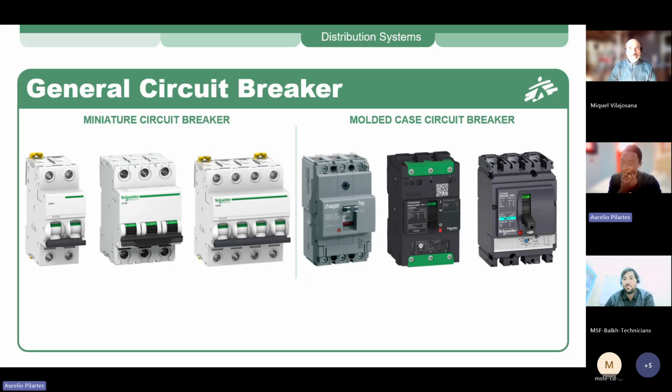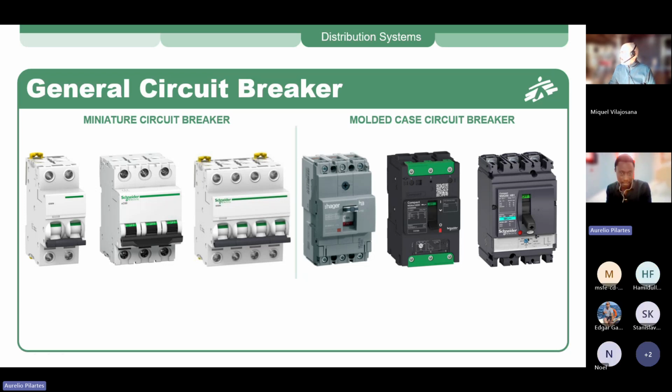Thank you very much. So there's no particular tool to allow you to do that, as far as I'm aware. I will have a deeper look at it and maybe get back to you. But as far as I'm aware, I don't think so. And yes, for more complex installations, it is always a good idea to include all factors, because they can influence the actual current flow, like the temperature, how you are laying the cable itself, the type of conduit you are using to protect the cable. All these factors could influence the current carrying capacity.